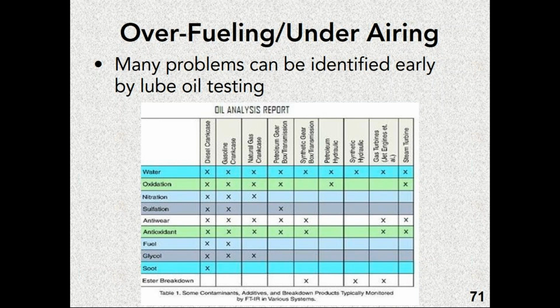The mechanics are very good at seeing those things and determining what's wrong with the engine. The problem with filtration systems, however, is that they're going to remove these indicators. The filtration systems are there to remove soot or particulate matter. Well, burning of too much oil or burning of anything which would produce particulate matter that the mechanic can use to diagnose is going to disappear because the filter is taking it out.